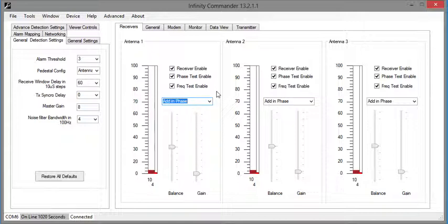If the antennas are set up so that the signals come in out of phase, so effectively you have a positive signal and a negative signal, then the signals can be used to subtract the noise from the 2 coils. So for example, you have noise hitting both the top coil and the bottom coil. By subtracting one from the other, you can eliminate the noise, or eliminate it to a great degree.